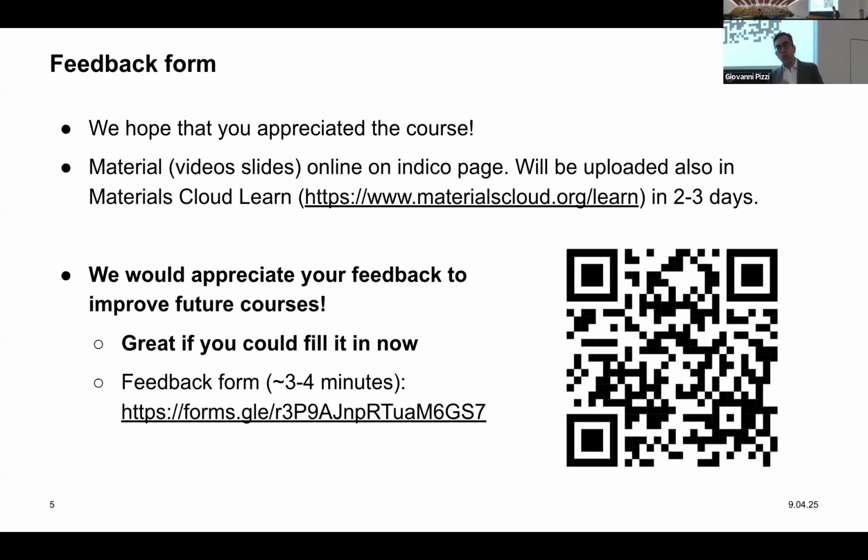One work which was very interesting a few years ago, and it's been a bit discontinued, was by a colleague of ours, Pietro Bonfa, one of those behind the Muon workflows, who developed a predictor of the time for a DFT simulation to run. Essentially, given the input, it would predict the time per SCF cycle. There's always been the hope, the idea of converting it, maybe nowadays also using machine learning, to have a heuristic that tells you, okay, with this input, I think it's going to run for this amount of time. And for me, even more than absolute time, which is harder to predict because you don't know how many iterations there are, you can get an order of magnitude, which is good.